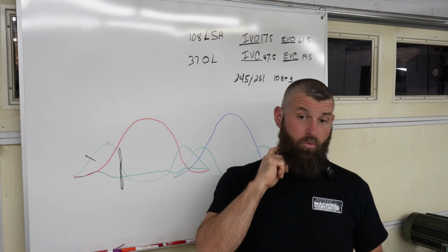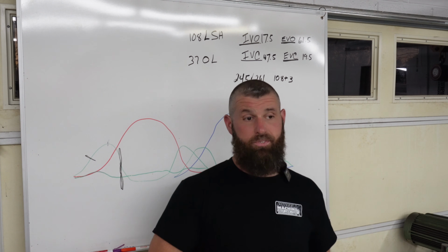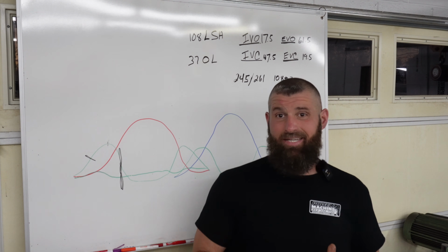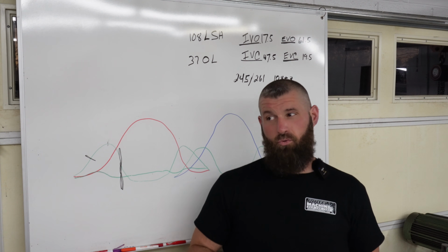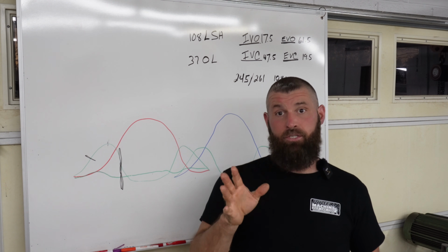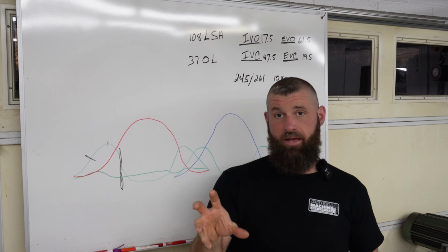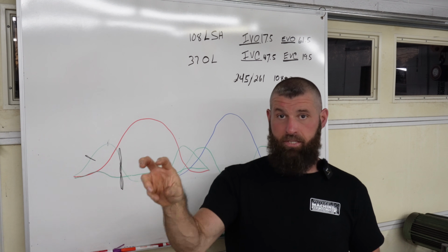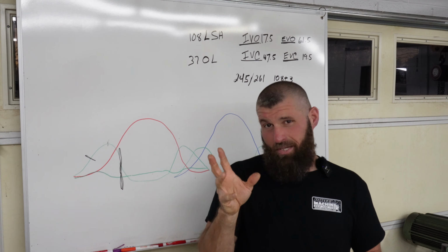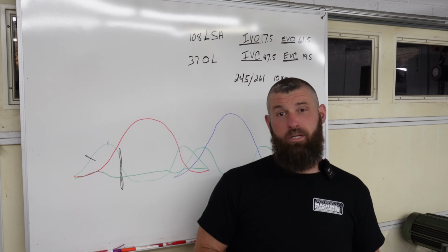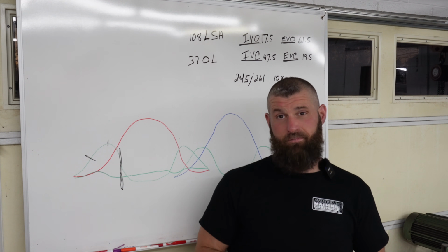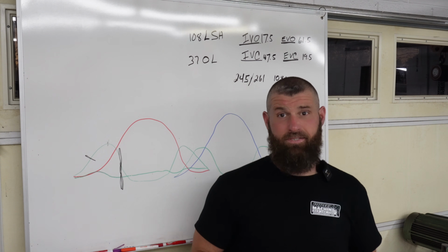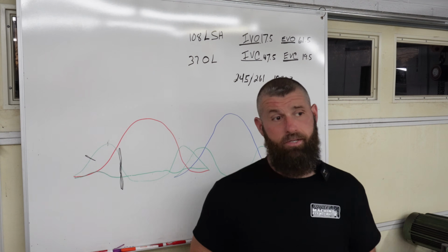A 427 small block Chevrolet that's going to go 7,000 RPM, to do a really good job and have a camshaft that's on the smaller side, so all the averages are big, torque's big, you need roughly about 330, 335 CFM. That's a lot of CFM. That's a lot of cylinder head.